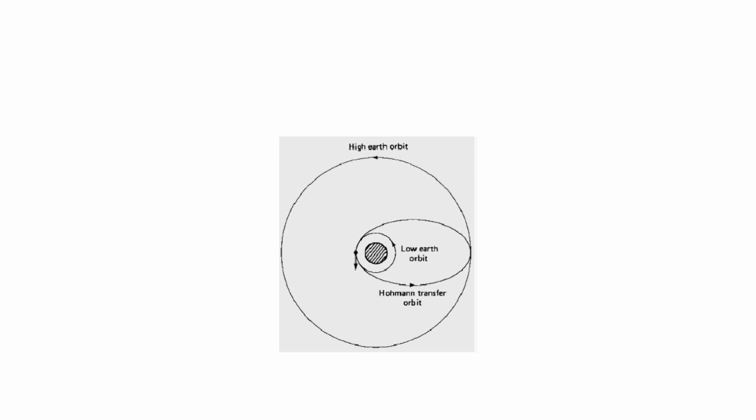So it takes a long time to revolve in this orbit, and once it reaches its maximum perigee as well as apogee distance, the perigee kick motor as well as the apogee kick motor is enabled, and from that particular position the satellite will be launched, or injected, into its corresponding desired orbit. So that is the higher orbit.